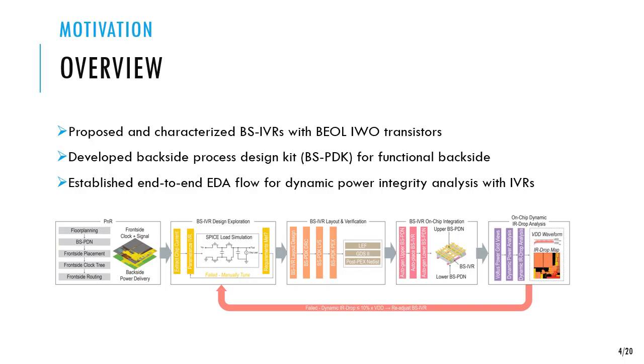And we repeatedly tune this till we have reached a desired outcome. Then, given our specifications, we do physical design, layout of the backside IVR. We go from the entire DRC to LVS to parasitic extraction flow using our custom backside PDK. Then we integrate our physically designed IVR into the backside, sandwiched between our backside PDN,